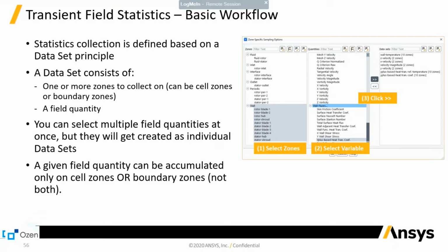And in the transient simulations, when you run a transient case, it mostly saves a lot of parameters and shows them to you, but when you close and open the file, they would be gone. So usually you need to have a data set and save it so it's accessible later. Now there's an easier GUI for it.